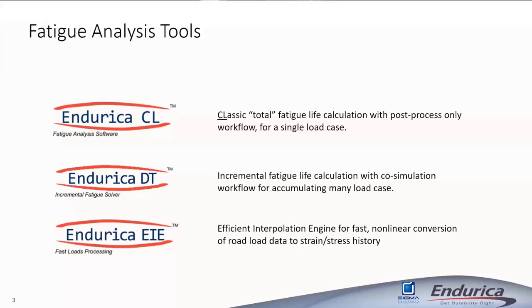That history is much longer than you're going to be able to analyze in a direct finite element run. So what you can do is use Endurica EIE to pre-compute some representative solutions of the part operating in different states. And then EIE can interpolate from your pre-computed solutions to generate the strain history from your road load data. It's very fast.